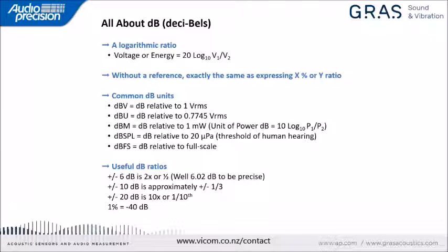And in that context, it's important to realize that, unless it's understood, something like 20 dB by itself has no meaning. Saying that is no more sensible than saying 42% by itself. Decibels only mean something when a reference is provided.